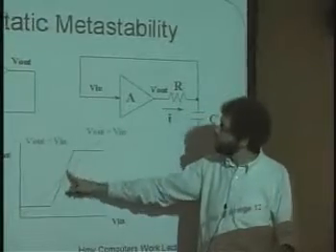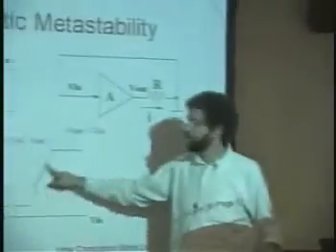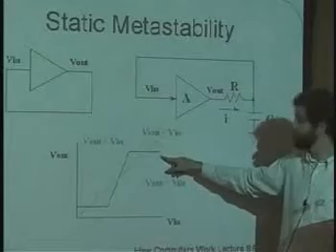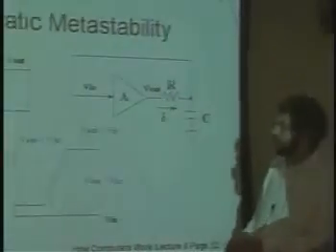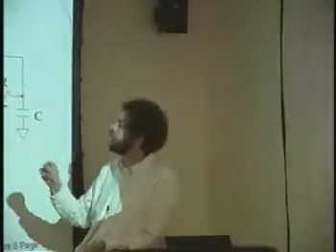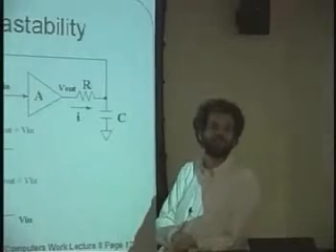And since the slope is greater than 1, it does what everybody who's played around with an audio amplifier knows. If you turn the gain up too high, it clips the output, right? And so within this range, it's a nice gain more than 1, but past a certain point, it saturates, and that's as high as it can go, and past this point on the left-hand side, it saturates, and that's as low as it can go. And it turns out that this is a wonderful thing, and it allows the device, when you hook it in feedback, to hold on to the value very well.